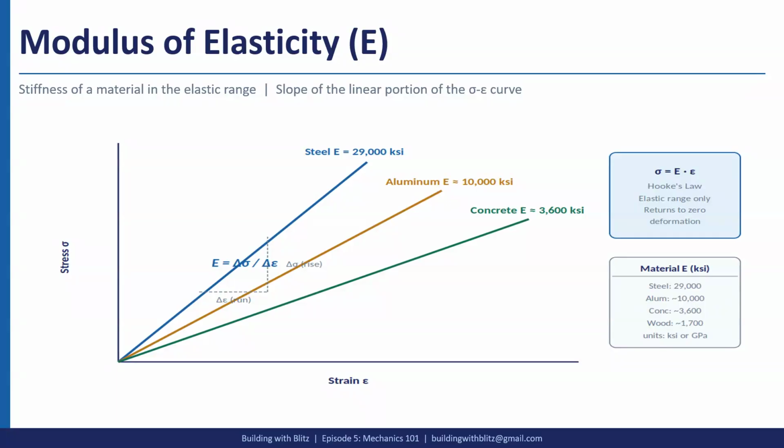And again, concrete is a non-homogeneous material. You have different areas that might have some more coarse aggregate or fine aggregate, water. It's harder, which is kind of why you have that rough, squiggly equal sign, whereas steel, you know what you're getting, so we have E equals 29,000 KSI.